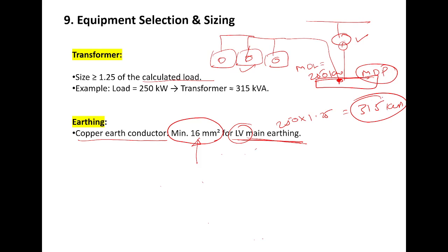If you are having a very big project, for that big or large load, we have to calculate the proper size of earthing. What will be the size of this strip? What will be the thickness? What will be the breadth, and what will be the minimum length? How many pits will there be? What should be the minimum resistance of this strip? Everything will be discussed and calculated in detail, but it is not possible for me to consider everything in only 2 hours.